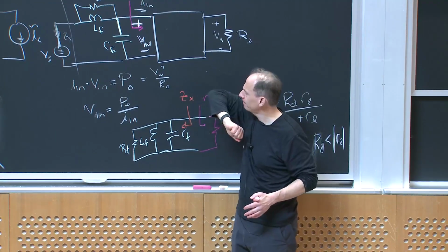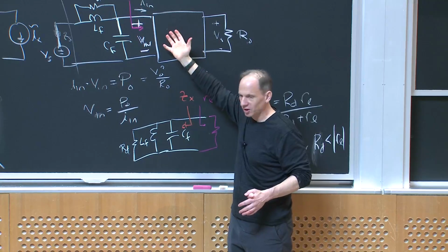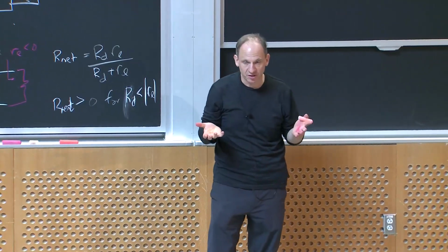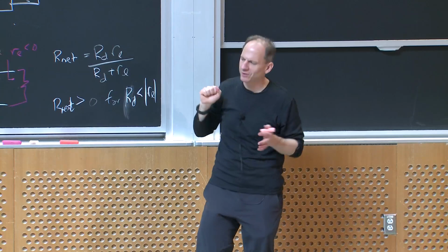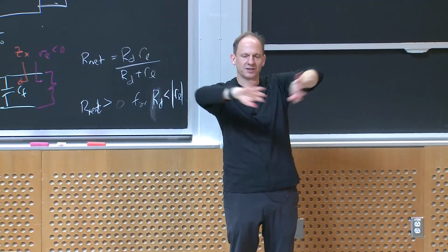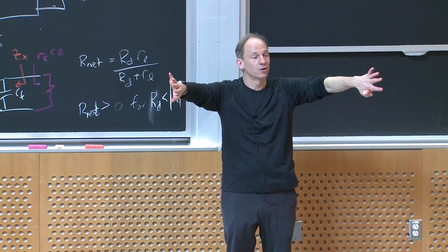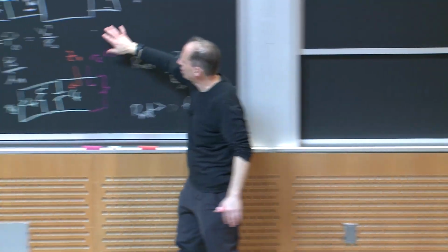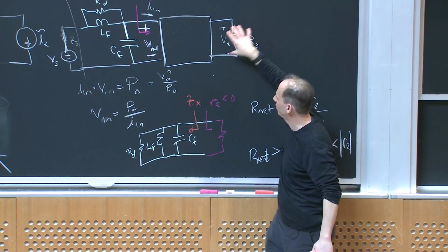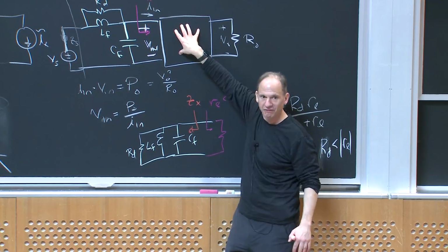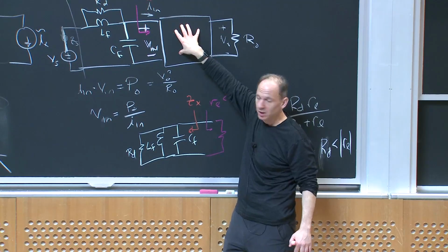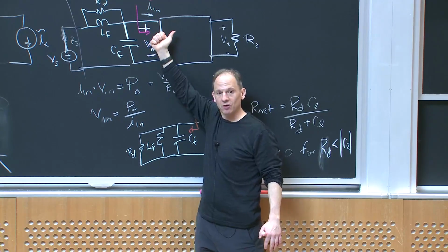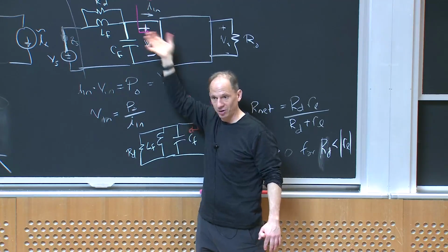But what they showed is an additional sufficient condition, although not necessary to getting a stable system, that you can ignore the design of the filter, or decouple the design of the filter from the design of your controller for your converter. Imagine instead of a perfect controller over the output, I just regulated my converter at fixed duty ratio, and I looked at the input impedance of the converter at fixed duty ratio across frequency, and that's going to be variable across frequency.